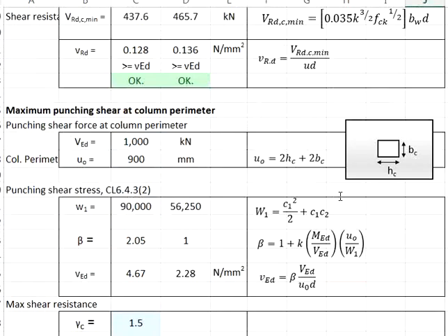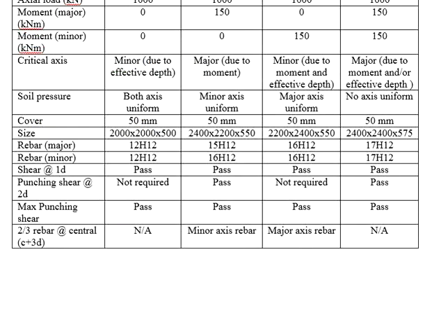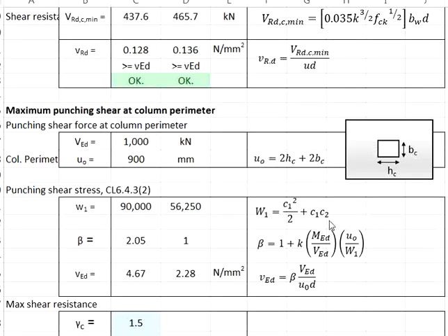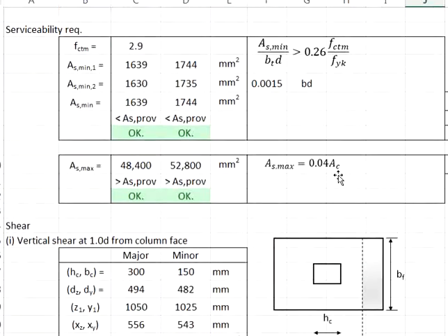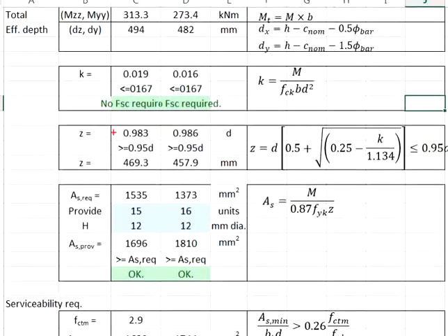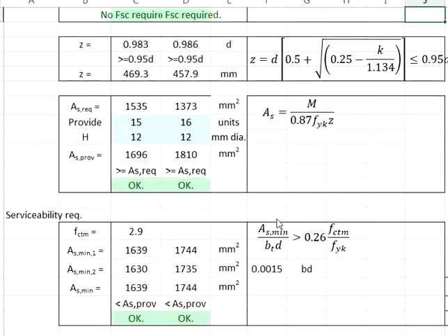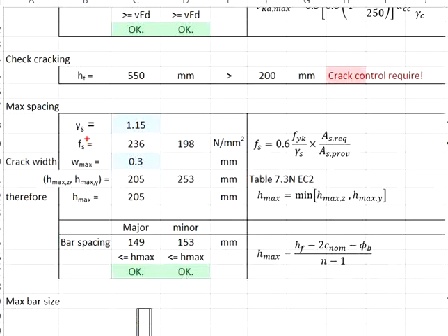But what is for sure? You can choose to only check the critical axis for the shear. To make it simple, to prevent the chances of underestimating the amount of reinforcement bar as well as the maximum spacing of the rebar, you might need to do both axes for the moment resistance, minimum AS and also maximum bar spacing.